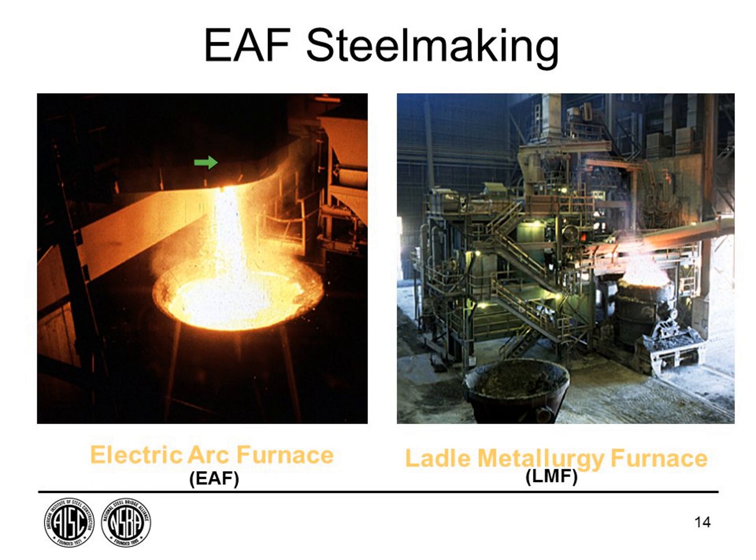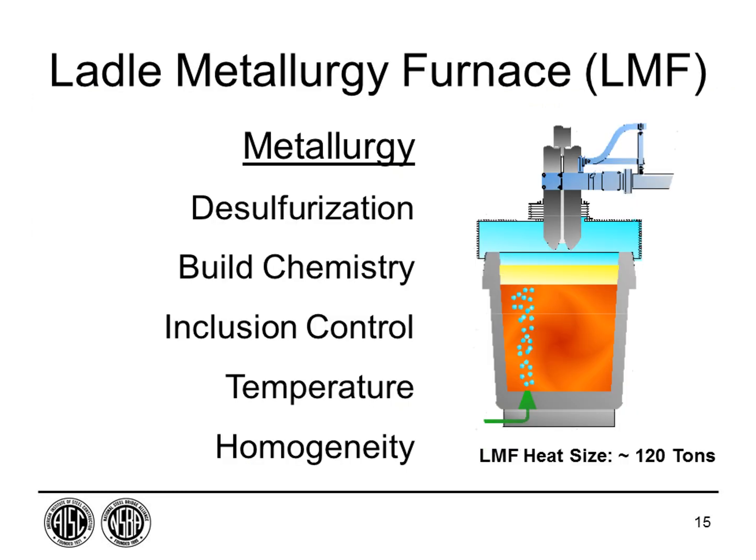After they melt it, the steel comes out of the bottom of the furnace, goes into a ladle, which goes over to another site where the steel is modified in terms of its chemistry. And this is done to refine the chemistry and to ensure that they get the quality of steel that they have. So after this process is done, the steel chemistry is sampled at this point. This is where the final steel chemistry is done. And it goes from here to a process that's rather new to the U.S. steel industry.